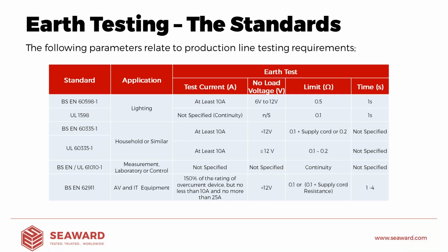For household or similar equipment, you can see the story is identical. Both UL and the British European standards require that we do the test at 10 amps from a supply no greater than 12 volts.